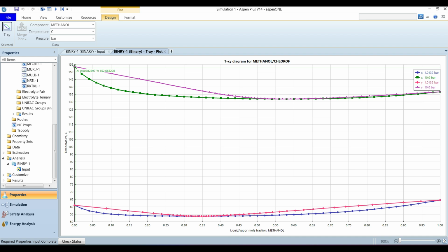This is how we can trick with the azeotropic composition, just installing a higher pressure device inside the two columns, and we can work with this azeotropic distillation and get almost pure components, one in the first column and the other pure component in the second column. This is how we can use this binary Txy analysis and conceptually develop a flow diagram that can be used to generate pure compositions beyond the azeotropic points.